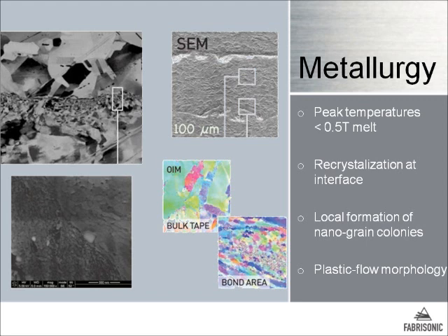So for all the metallurgists out here, here's a little more information on how the actual ultrasonic bond is being formed. As we said, we've studied the process of ultrasonic metal welding for years, and we believe the bonding mechanism on our process is, in fact, dynamic recrystallization. When you take large grains, such as seen in the top left picture, and you shear them at a very high rate, their surface energy requirements actually changes under high shear. And the surface energy and thermodynamics drive a preferential grain size that is much smaller.